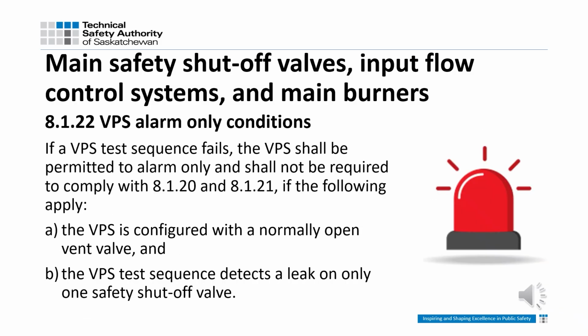8.1.22 VPS alarm only conditions. In this situation, since both VPS and normally open vent valves are used in combination, allowing the VPS to alarm should be permitted since the vent valve prevents gas from entering the downstream combustion chamber. By alarming only, it allows the system to be operated but also notifies the owner that valve maintenance needs to be scheduled.